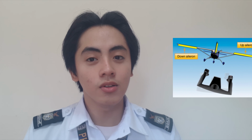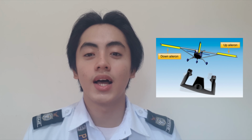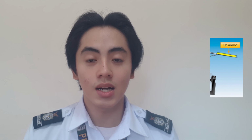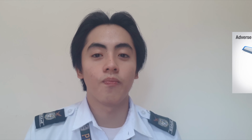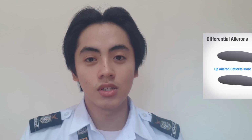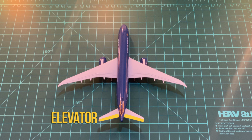The one with the aileron down will have increased lift, while the aileron in the opposite direction will have reduced lift. The difference in lift force produces an undesirable effect called adverse yaw. This is the tendency of an aircraft to yaw in the opposite direction of a roll. There are methods to counteract the adverse yaw. They are the use of differential ailerons, which is the most popular method, the Frise aileron, and the aileron-rudder coupling system.